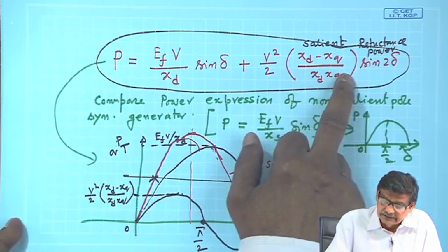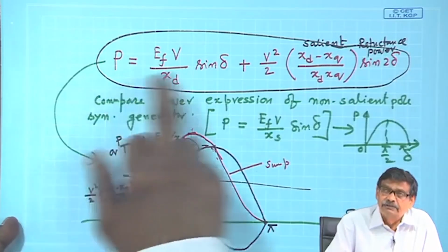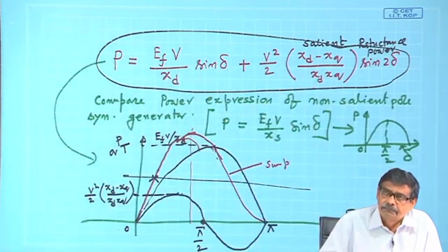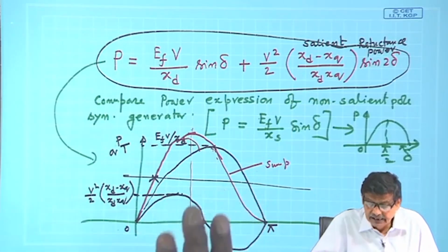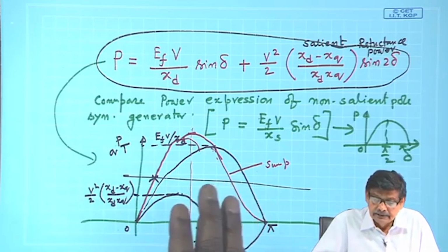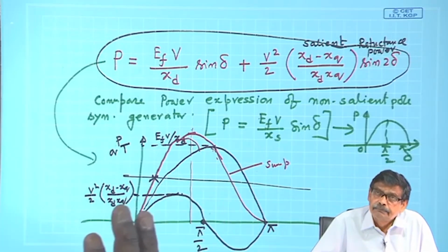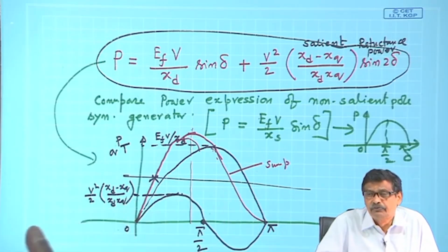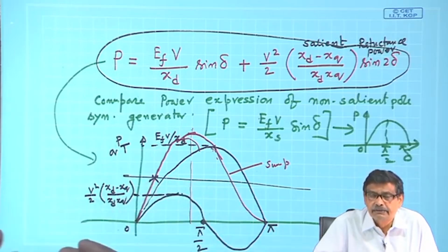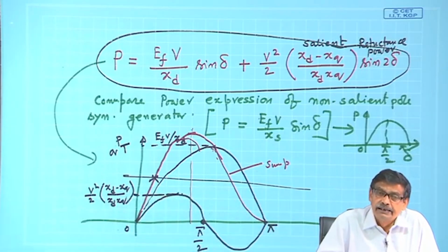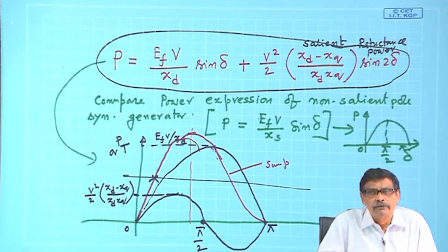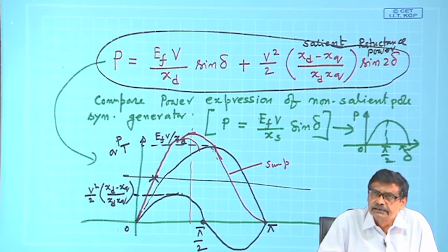That is, there will be no effect of excitation on this term. So, for a salient pole synchronous machine, I know how to draw the phasor diagram correctly, how to fix up the q axis, d axis, because I A is to be resolved into I d and I q, and their effects are to be taken into account by two reactances x d and x q.